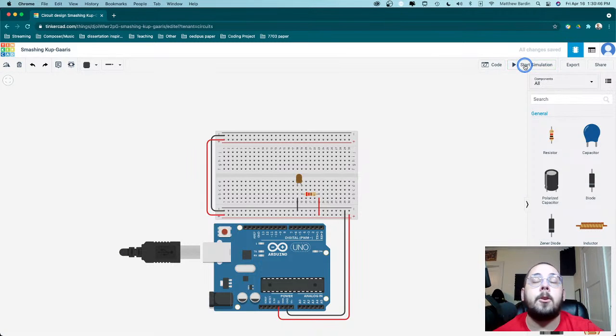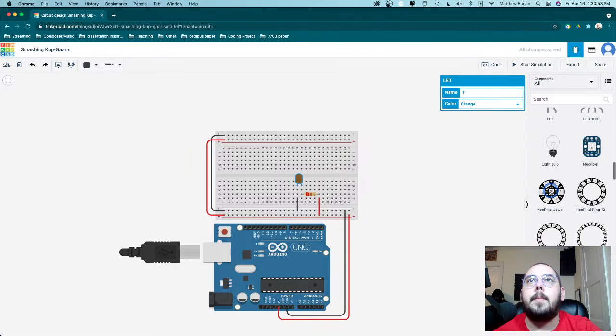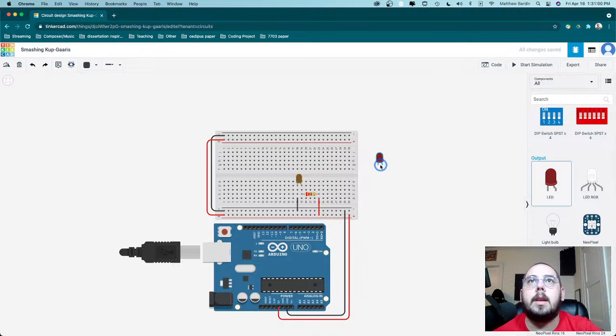And this is actually going to be the first circuit that my students make, is just wiring up an LED. You get that 220 ohm resistor. They can pick what color it is. It's a little hard to see in this diagram. If we pull out an LED, you'll notice that one of the little terminals is straight, and the other one kind of pivots out. On the physical LEDs, one side is longer than the other, one little wire.